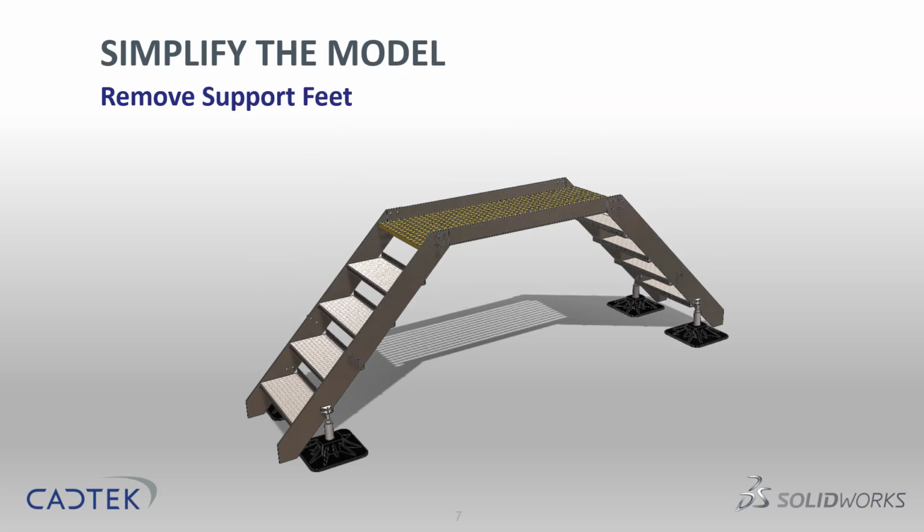These gantries rest on these brought in items, these heavy rubber feet. Now we don't design those, we just buy those in, we know how strong they are, so I don't need to test those, they're not doing anything for our design. I do need to take into account how they're supporting the gantry, but I don't need to actually test the feet themselves.